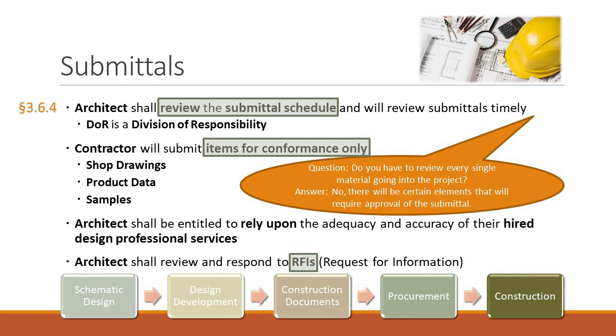Okay, great. So it continues on. Contractor submittal such as shop drawings. Sometimes you're going to put in your drawings a series of columns and the beam, but you're not going to show how those bolt connections go. So the contractor and its steel subcontractors can go out and create shop drawings, or how the electrical is going to work, or how the plumbing, mechanical. Those are shop drawings. And they're going to do the more detailed drawings of what it looks like. So that's a shop drawing.